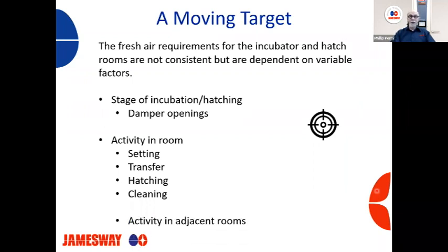Another thing that affects our fresh air requirements is the activity in adjacent rooms. I've gone into hatcheries, especially hatch rooms, seen a hatch room go negative, and come to find out that the washroom exhaust fans were turned on, and there was no makeup air for the washroom.